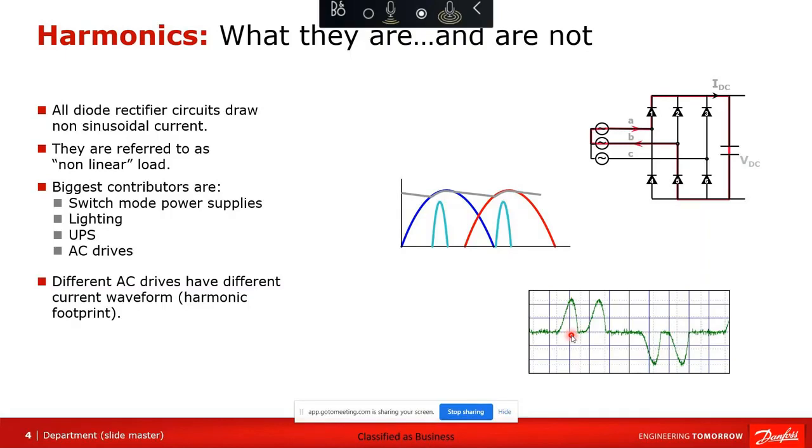The harmonics portion of that system is based on the front end, or the rectifier system. In the upper right-hand corner, you can see what's called a 6-pulse diode rectifier. There are two diodes per phase, and you can see A phase, B phase, and C phase right here, and you can see each one has its own diode.